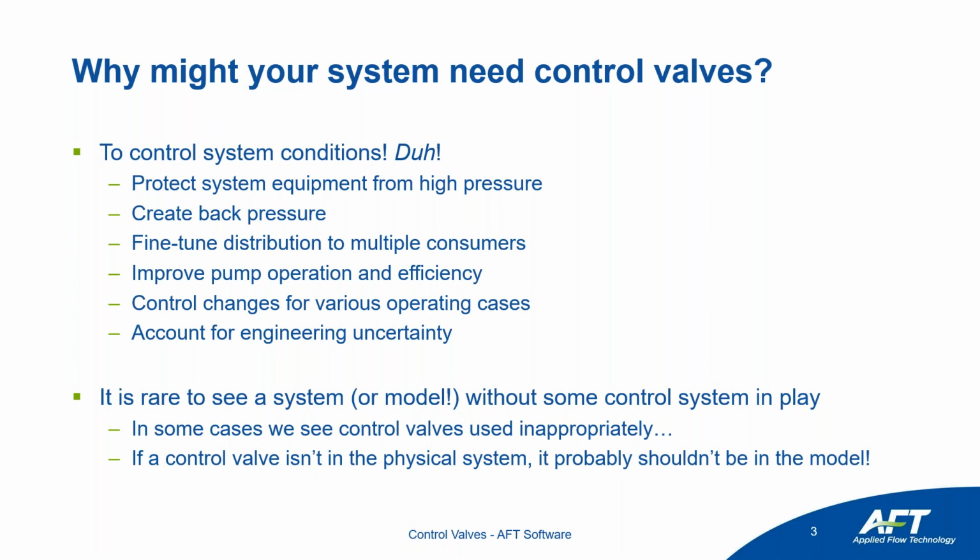So as long as you rely on that rule of thumb, again, a control valve, if it's not in the physical system, it probably shouldn't be in your model because you're applying additional boundary conditions, whether that be pressure specifications or flow specifications. There are some exceptions, but again, with all rules of thumb, this is going to take care of most cases.